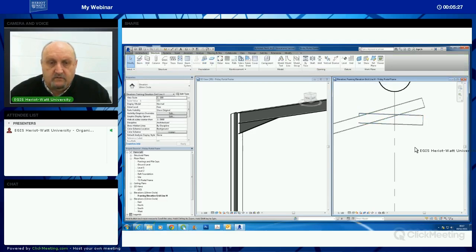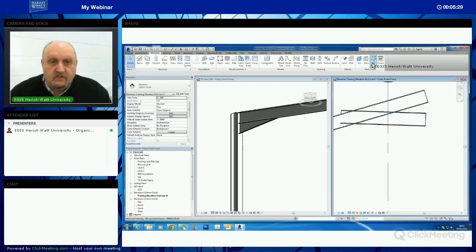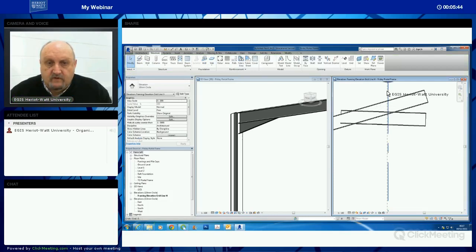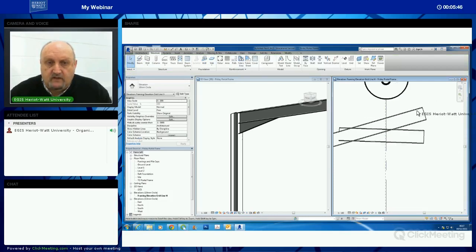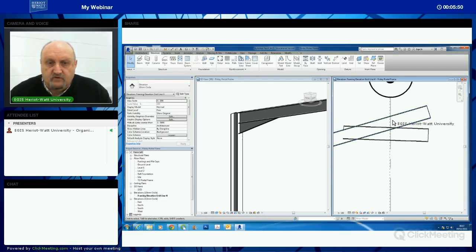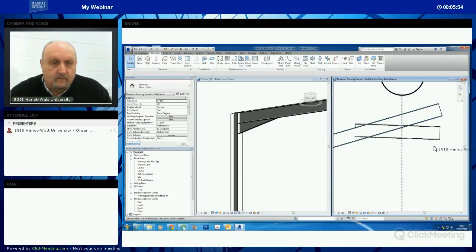And that looks to me to be about right. And then reference plane, and then again remember, pick line, and this time we need an offset of 25, not always 25. I've started going at 25, so I'll keep going with 25 as reference plane to offset from the middle grid line 3 by 25mm, and these will be trimmed just short of the centre of the structure.